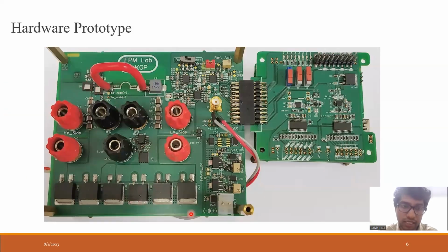These are where the load resistors are placed. And then there are certain sensing components. These signals go from this power board to this signal conditioning board. They're connected via this header. And then there is a DAC and an ADC present. And these are certain user push buttons.